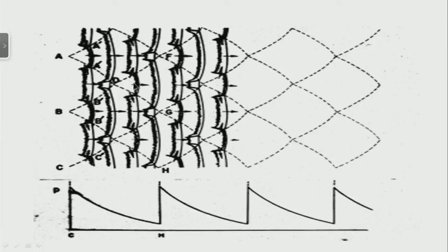Therefore, the procedure by which a detonation propagates is, I have the triple point intersection over here, I have a Mach stem being formed, behind the Mach stem rapid chemical reactions are occurring. I am just considering the events within a cell of detonation. We will take a look at the neighboring cells shortly. Within the Mach stem, chemical reactions occur rapidly, it drives it, but during the process of travel, the Mach stem shock decays in strength, maybe it starts with a strength which is around 1.2 to 1.3 times the mean value of the Mach number at which it is proceeding.